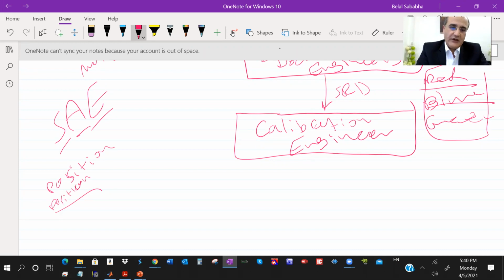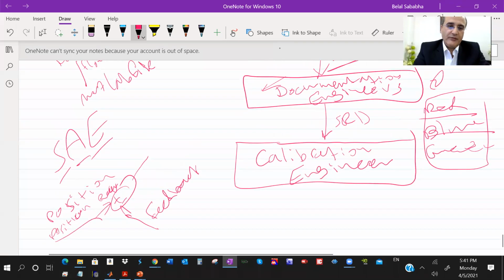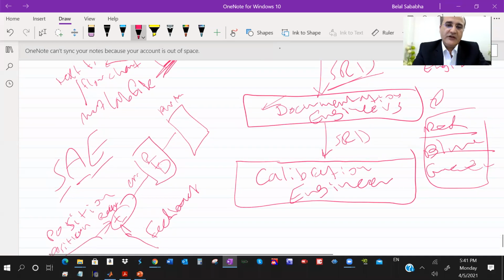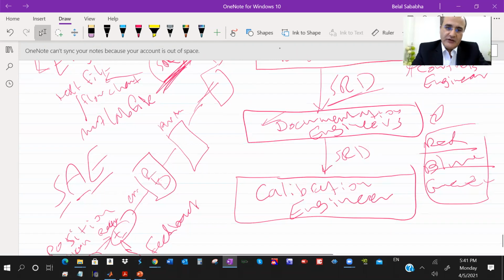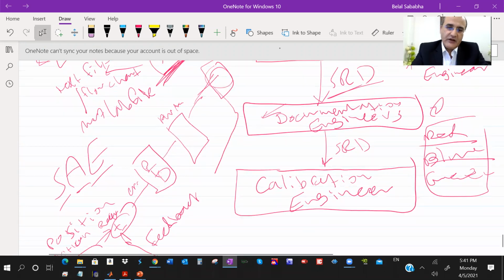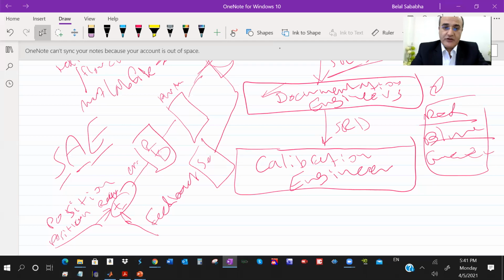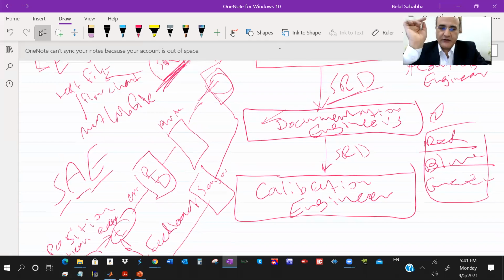Of a throttle body. You have a required position. You get feedback from sensors, right? You take it to a PID controller, the error. Okay, you produce the required, for example, PWM for the throttle body, reflect on the throttle body, for example, position, right? And you get the feedback through a sensor that measures the angle, and so on, to control the position of the throttle body.